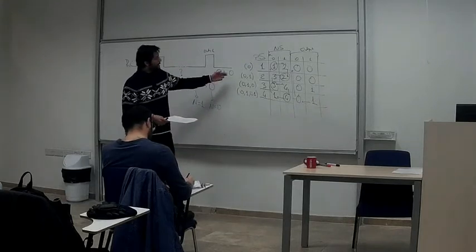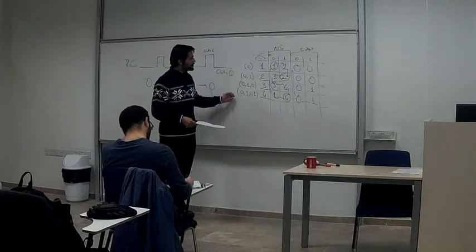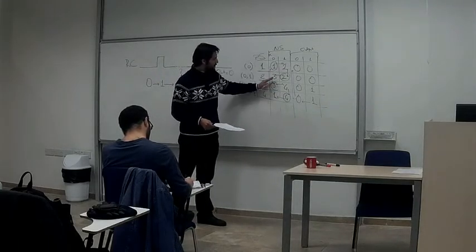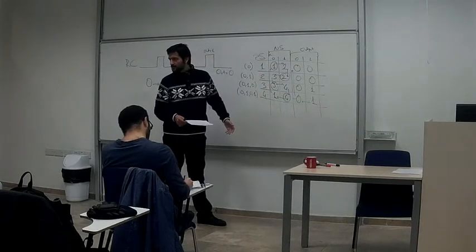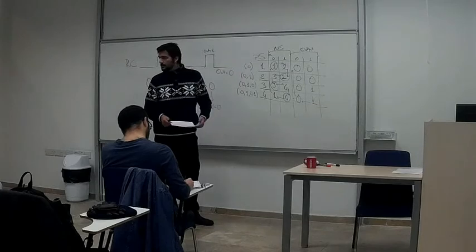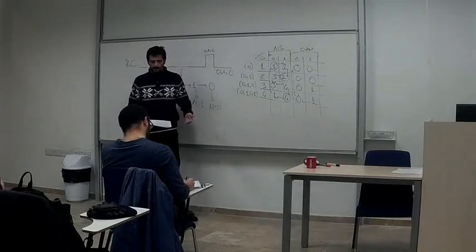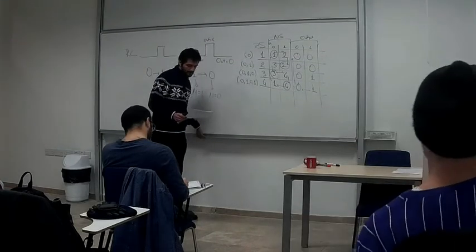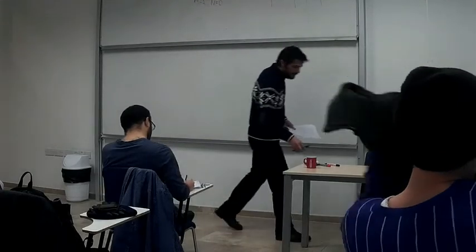And okay, so anything to reduce here? All have individual meanings. We have 1, maybe 1 here, but 2, 4 doesn't count. We don't have any don't care, so it's really hard to reduce it. It's not reducible. So this is also the flow table itself. Okay. Let's transfer it to the transition table.